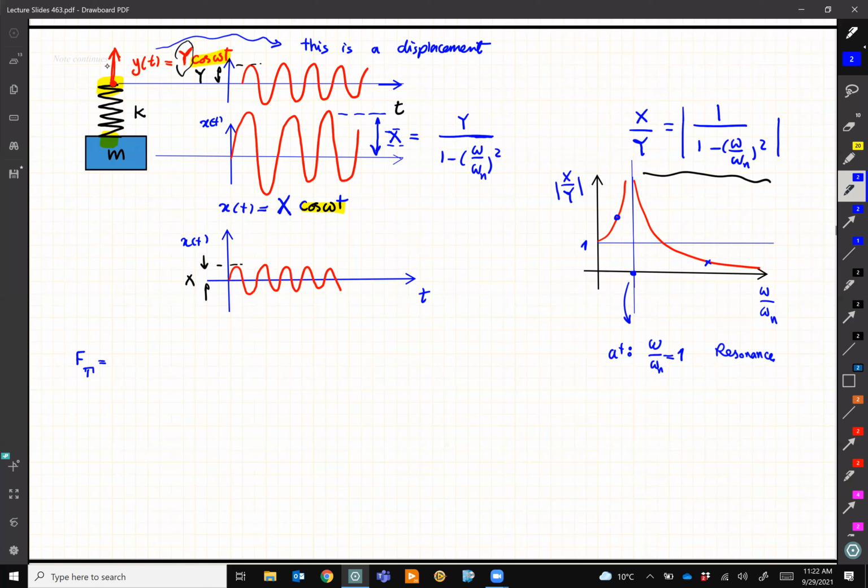Right? This Ft, we say that it is k times (x minus y), whatever deflection I'm going to have in this system. All right. So the difference between x and y. So in this example that I showed, maybe this is x that we selected, because we tend to select the direction of the coordinate. If I know what my excitation is, like right now it's going up, we'd better show x like that. However, it doesn't matter.